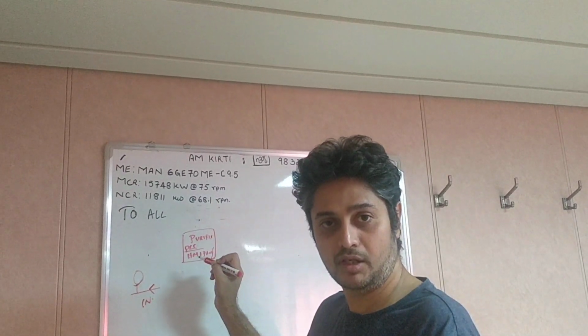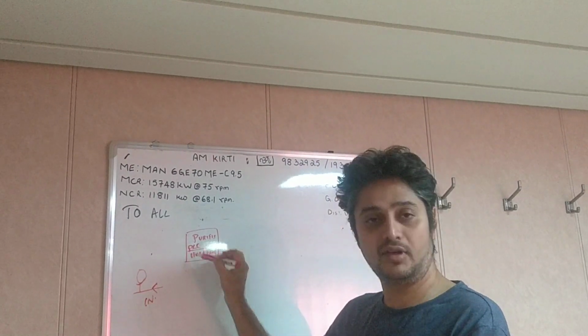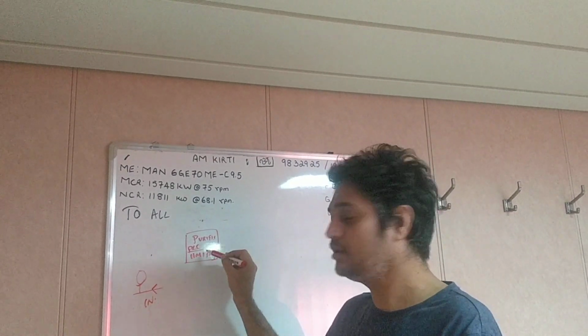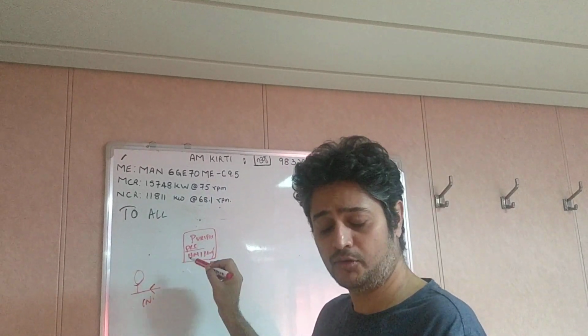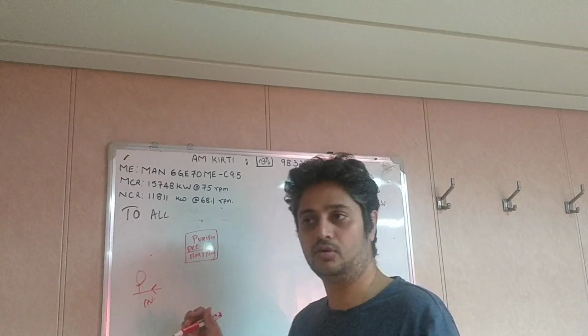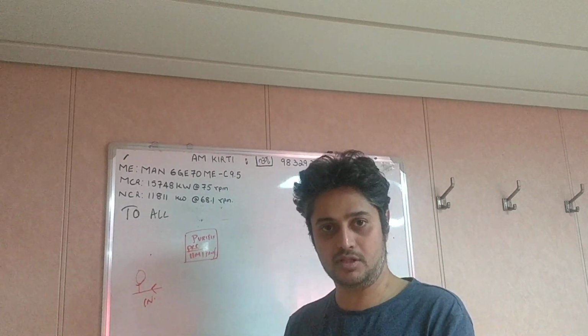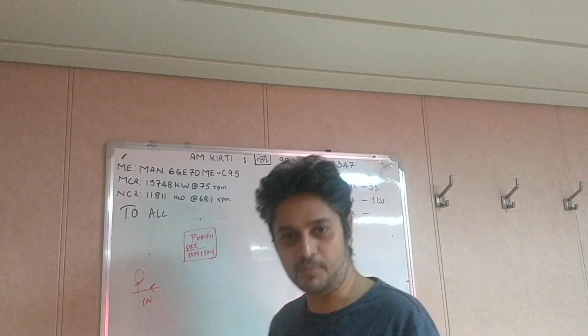Inlet temperature should be at 98 degrees or something, and low temperature alarm, all settings are inside the panel. Once you log in using your username and password, you can change the settings. And as you know very well, there are certain settings which you can't change, which may ask for an admin password. Okay, I will come to that later.